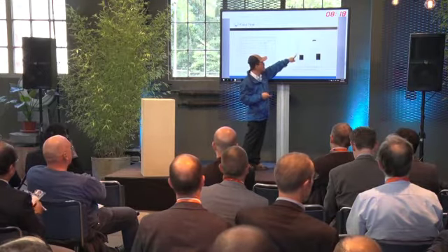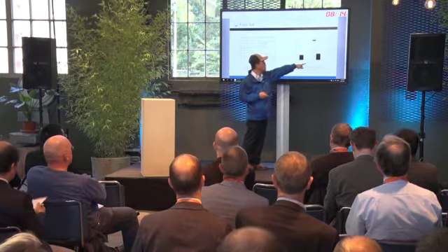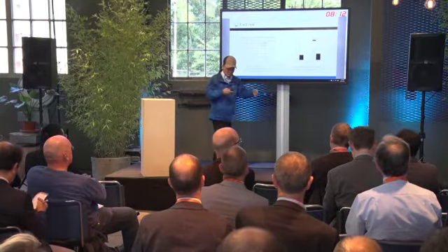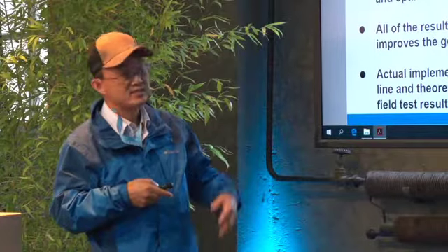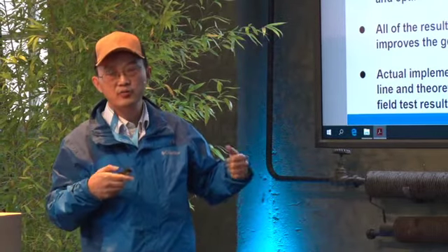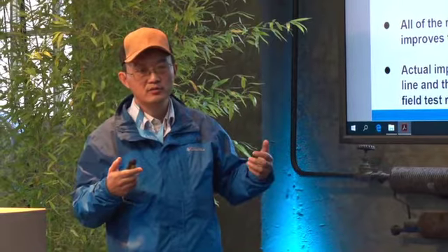So this is before grinding, and this is after the grinding. This side is the top wear. They also changed. So we can extend the rail life by grinding with properly designed rail profiles.